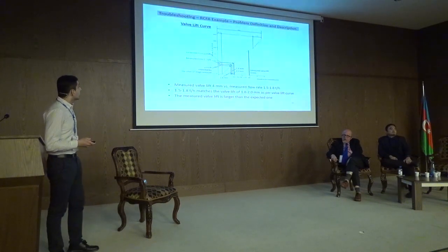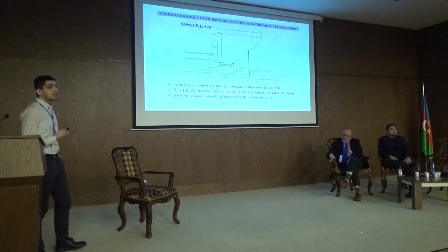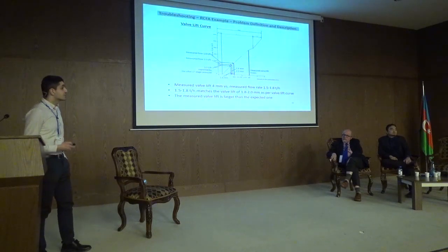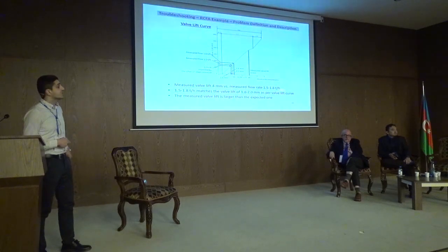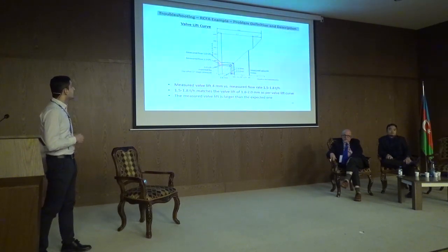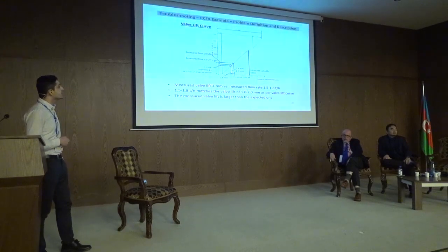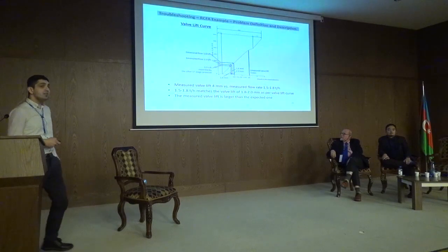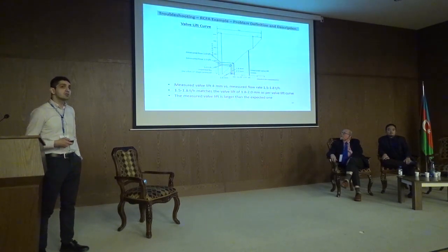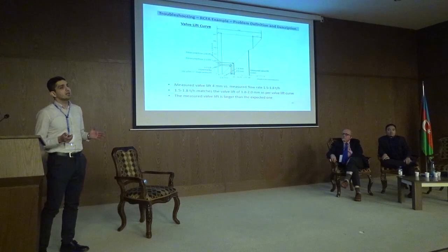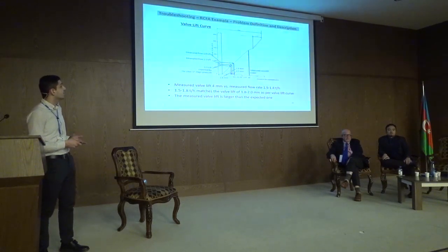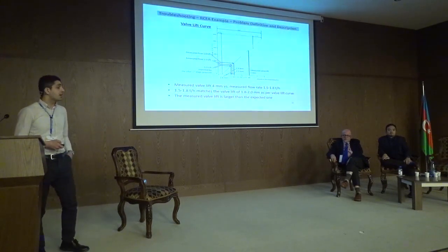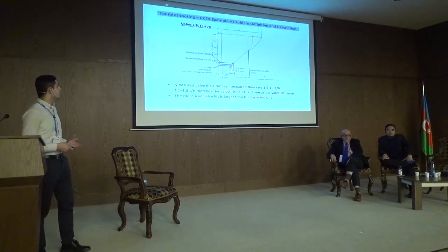Okay. So here we have the typical expected valve lift curve from the manuals, from the data sheet of this specific steam turbine. Here the steam flow rate is plotted against the valve lift. We did a turbine solo run test, because before we can do the MRT, mechanical run test, connect the coupling and do the mechanical run test, we have to do a turbine solo run test. We have to ensure that the turbine is in a good condition.